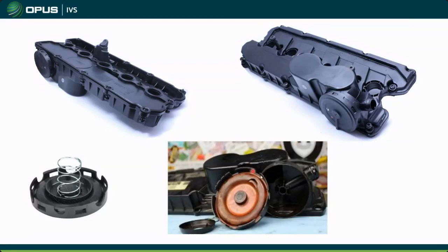And you'll often hear these whistling when they're bad in various makes and models. They all work very similarly, and they have a similar presentation when they fail. Usually you get a high-pitched squealing noise, mostly when the engine is warmed up, and you'll see this issue repeating as we talk about more and more different engines.